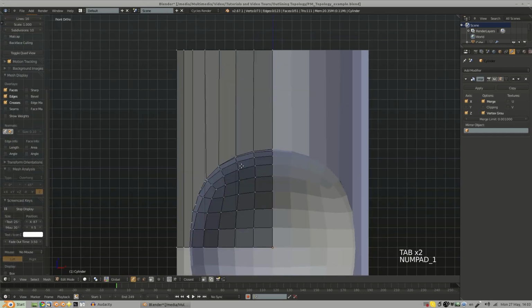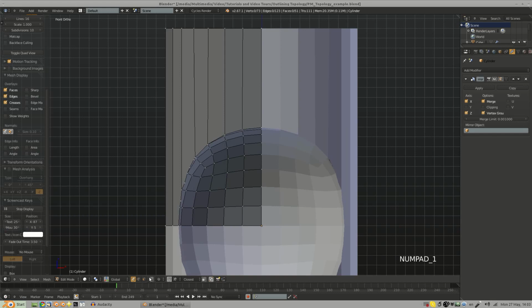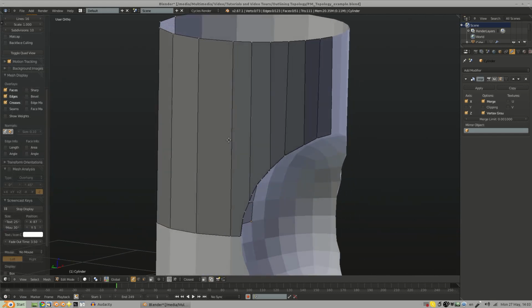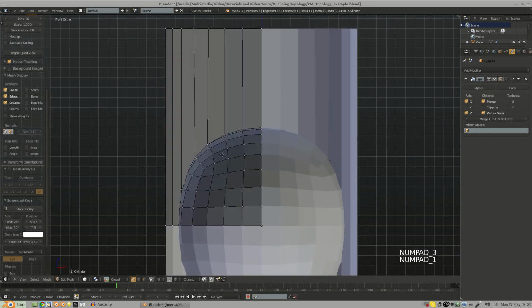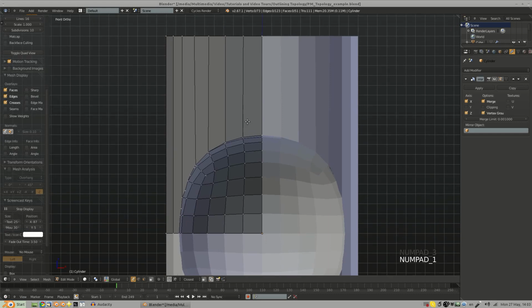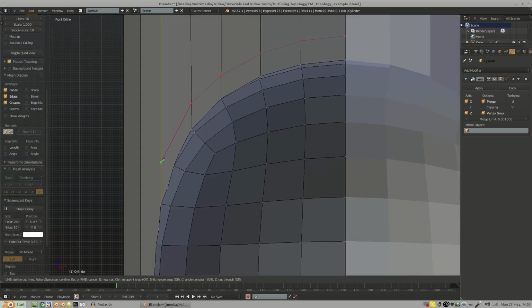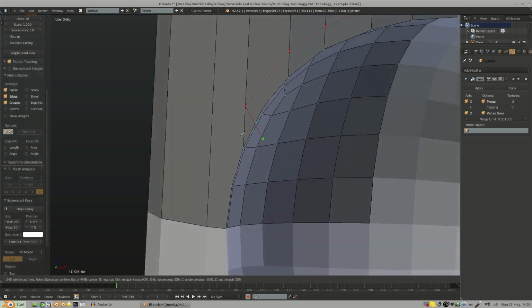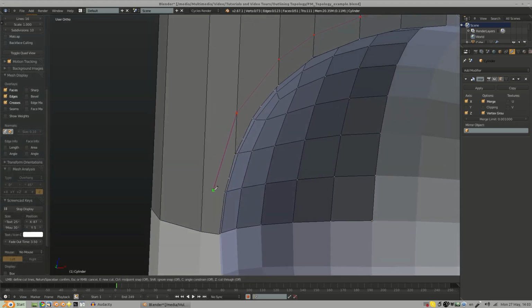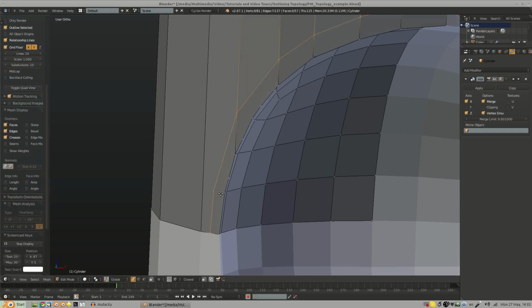So back to our knife tool. So I'll just enable the background geometry thing so we don't cut the edges behind it. Excuse me. So I'm going to call up the knife, add in my vertex points here, and we're going to encounter a couple of things while doing this, like a few problematic areas and so on. But we'll work on those when we get to them. So I'm going to add one right down the center here, and then confirm it.